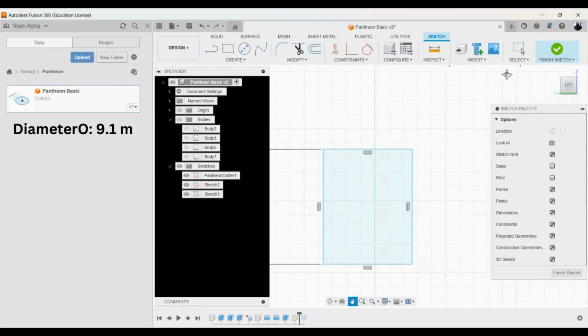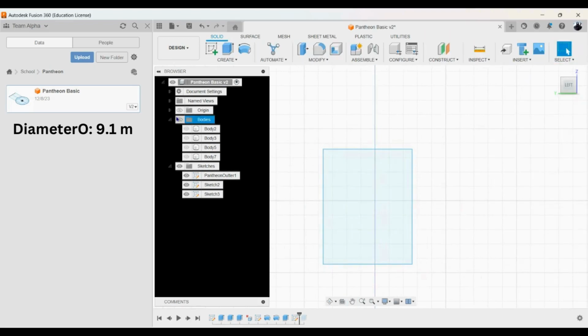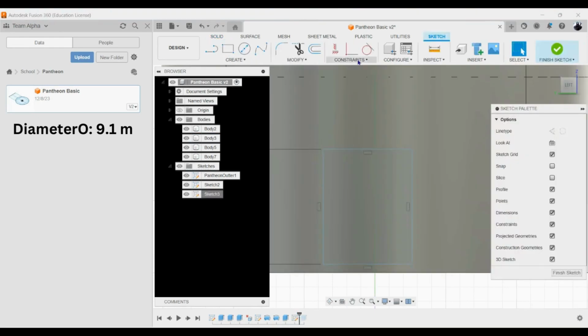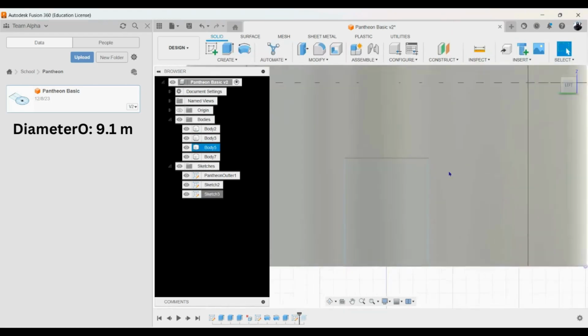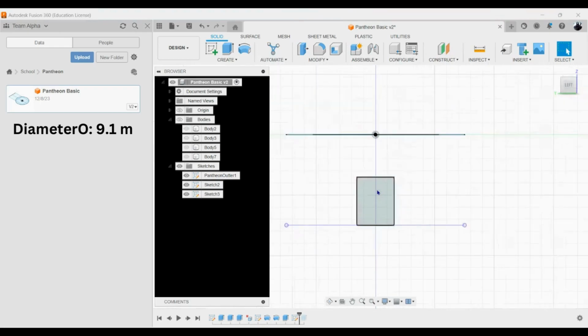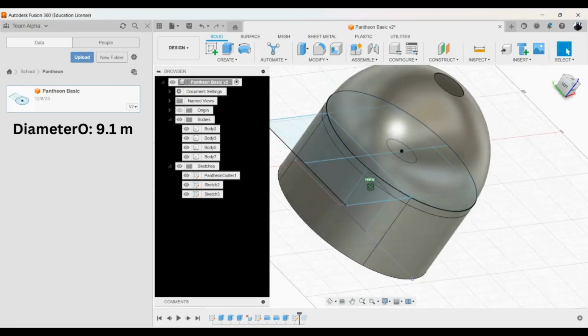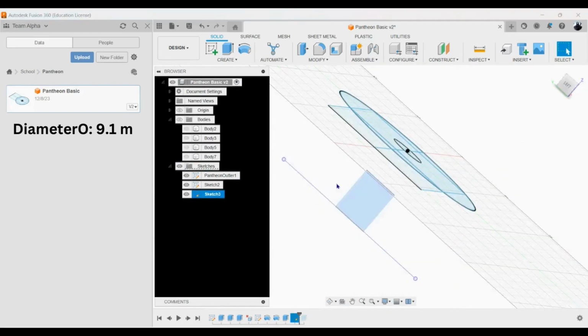In the rest of the video, I try to stick as much to scale as possible by making the width thinner on top to mimic the design of the actual Pantheon. The closest I can get is showing the general dome shape. Without the oculus, that point of the dome has the highest tension, from natural shape as well as rainfall. The strategic use of lighter materials at the top, where the dome is most vulnerable, helps reduce stress and potential collapse.